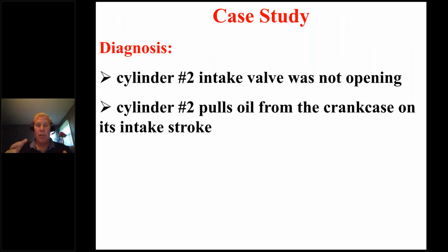And let me just kind of wrap something up here. Theoretically, if valves don't open, you can't get air in or out of the cylinder. So if an intake valve doesn't open, you have to ask yourself, as bad as 16 PSI is, air came in and air comes past the rings, just like it did at the very beginning of our conversation with that 5.3 GM AFM engine. It gets past the rings.